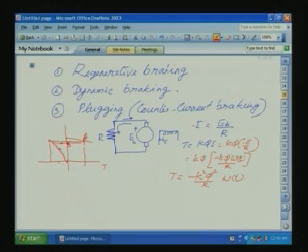But what we want is not to stop. We want to see here also it is dissipative, dynamic braking is dissipative, but in many medium power applications the power is very small because this resistance is not connected continuously, only for a small duration during acceleration and during decelerating the machine or trying to stop it. So momentary dissipation is possible.